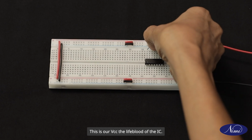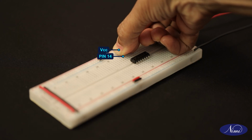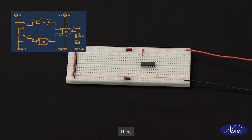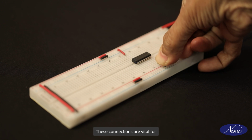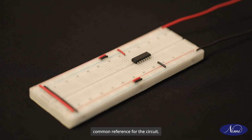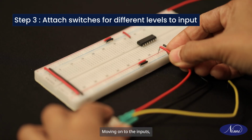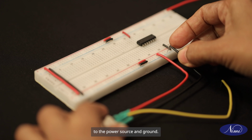Next, connect 14th pin of the IC to the plus 5V power supply. This is our VCC, the lifeblood of the IC. Then, make sure pin 7 is connected with the ground. These connections are vital for providing the necessary power and establishing a common reference for the circuit. Moving on to the inputs, connect both terminals of the toggle switches to the power source and ground.